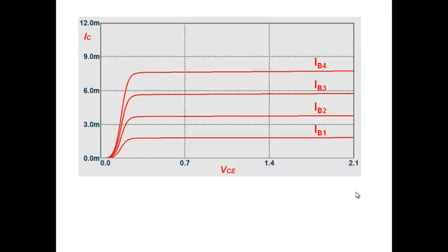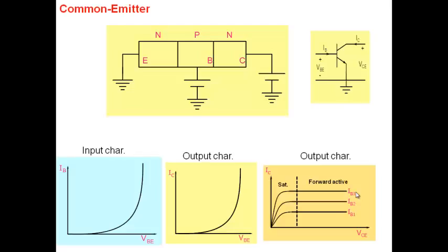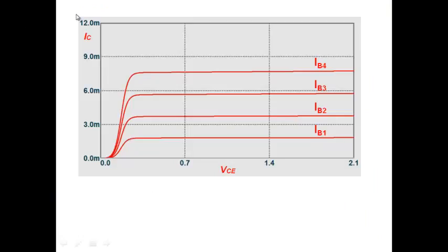Okay, so let's come back to this. This is an important characteristic here. Whenever you're handling a transistor, if a transistor is given to you in the lab and you want to check, is my transistor working properly or not? Well, this is the signature. Try to measure: force a certain current into your base, say 10 microamperes, 20 microamperes or whatever, plot IC versus VCE, see if you get this or not. That's the signature of a transistor.